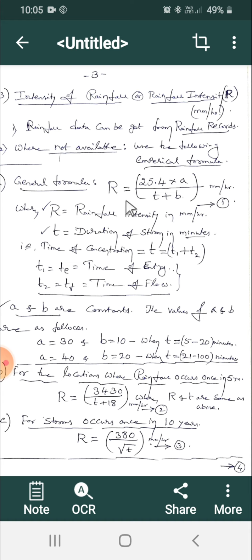See, A is the catchment area in terms of hectares that is available in the map, and then I is what you call the impermeability coefficient. I is I1, I2, I3, A1, A2, A3 is the reference area. Okay, let us see one by one afterwards. Then R is this one. This is what you call the general formula.